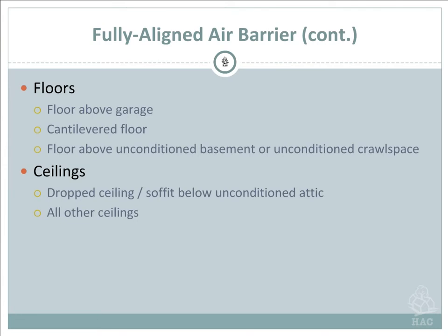I'm an old believer in foundations and crawl spaces. If you've got a crawl space that's at least 3 feet high, where you can get in there to work around, I would insulate the perimeter of the foundation instead of doing the floor, and we'll talk a little bit about that. Drop ceilings, soffits below unconditioned attics. Again, these are all other ceilings, and we'll show you examples of these.